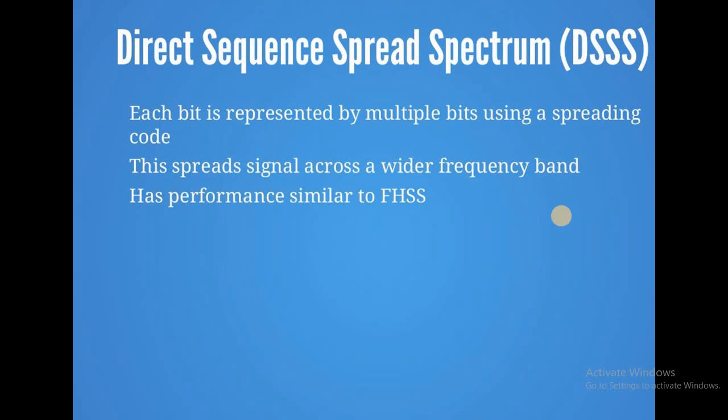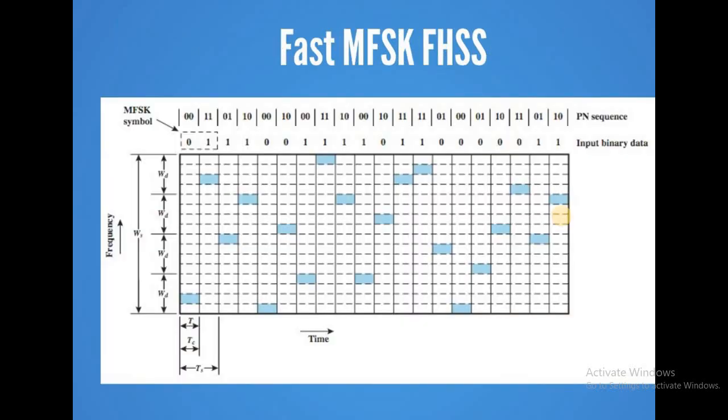The advantages of frequency hopping are that the synchronization is not greatly dependent on the distance. The serial search system with FHSS needs a shorter time for acquisition. The processing gain is higher than that of the DSSS system. A disadvantage is that the bandwidth of an FHSS system is too large, and it is complex and expensive. Digital frequency synthesizers are required. The main FHSS applications are Bluetooth and walkie-talkies.